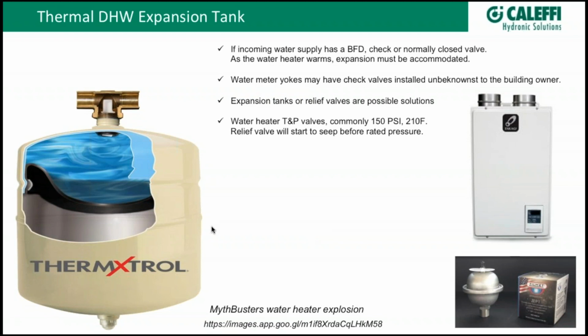Yeah, that's a good point. Some of the valves out there have a bypass that lets water go backwards, like Cody was saying. But if your pressure out there is higher, you can't push against pressure that's higher than what's coming in. So that's not an absolute protection. You really want to consider putting the expansion tank. And I think, like I said, some of the codes are requiring it now.